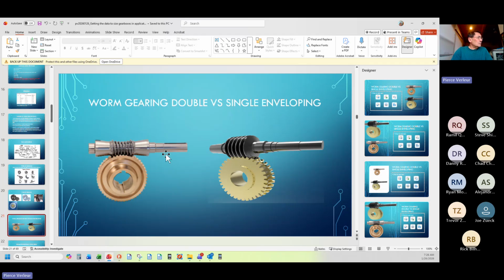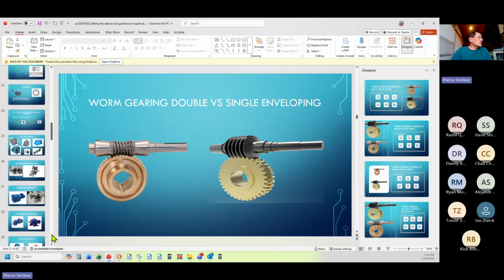So this gearbox here versus this gearbox here, you're running 80% roughly efficiencies versus 60 to 70%, but both have starting torque issues due primarily to the stiction of this geometry. Size accordingly.